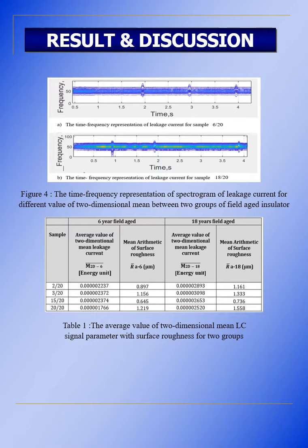This is because the electrical power source applied to the insulator using the IPT test is 3.5 kV with 15 Hz frequency. It shows the energy obtained in the 80 year sample is higher, represented in orange color tone, compared to the 6 year sample. Therefore, the signal energy can be illustrated by the color intensity legend, whereby the energy increases in response to increasing value of two-dimensional mean.